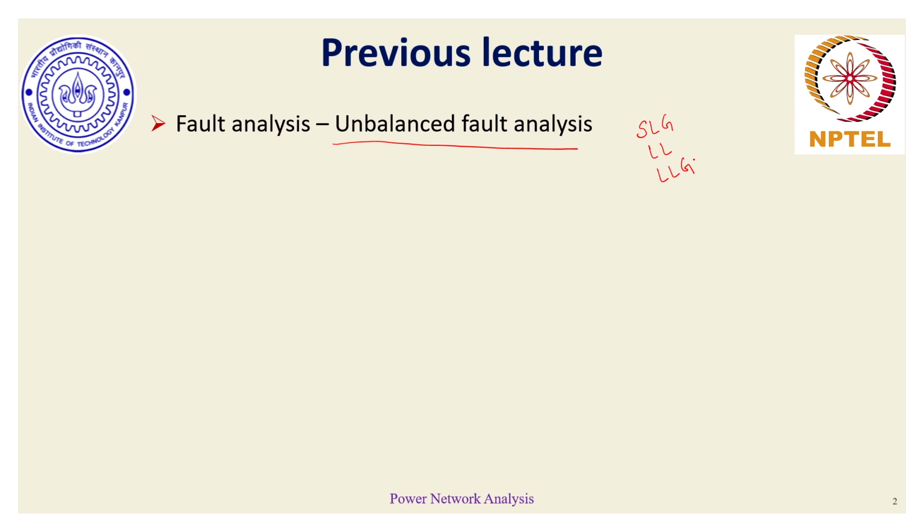In all these analyses, our most critical assumption was that the pre-fault power network in which these faults could occur, and it could also happen for the three-phase balanced fault, is assumed to be a balanced network. That is the big bottom line assumption behind the application of Fortescue's or Thevenin's theorem. The analysis might be different if this preliminary understanding of having pre-fault balanced power network operation is not valid.